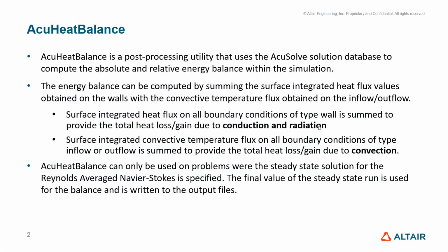AcuHeat balance is a post-processing utility that uses the AcuSolve database to compute the energy balance within the solution, and it is mostly used for a steady state solution of the Navier-Stokes equations. Wherever a wall boundary condition is applied, the surface integrated heat flux is calculated and summed up to provide a total heat loss, for conduction and radiation.